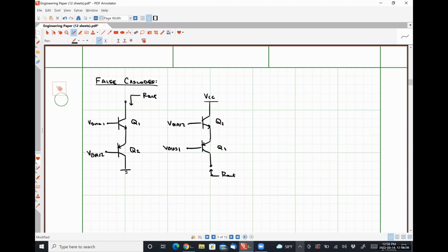So fundamentally, we are degenerating our current source stage by a very small resistance, which is exactly the opposite effect of what we are trying to do, okay? So it is very, very important that we degenerate our stage with the same type of transistor so that we avoid one of these diode connected devices, which lower our output resistance appreciably, right?